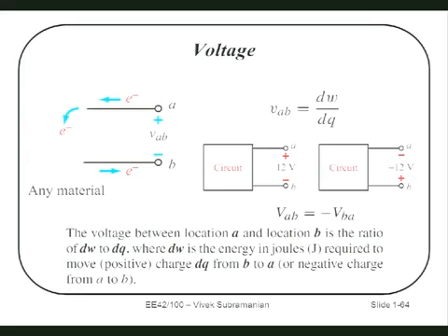Now, remember something important. Voltage being a relative measure, it depends on your reference. So if I'm referencing relative to point B, I would say point A is at 12 volts. If I'm referencing relative to point A, then I would say point B is at minus 12 volts. Because it's all relative. It's just about how much energy change there is, how much work you are doing. Okay? So you should keep in mind that if you flip the orientation, remember to flip the sign for your voltage. That's going to be an important rule when you start doing circuit analysis, because you will find times when you're counting voltages in the opposite direction to the way the voltage was defined.